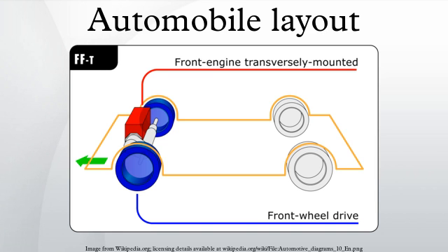Characteristics. Front-wheel drive gives more interior space since the powertrain is a single unit contained in the engine compartment of the vehicle and there is no need to devote interior space for a drive shaft tunnel or rear differential, increasing the volume available for passengers and cargo. There are some exceptions to this as rear engine designs do not take away interior space. It also has fewer components overall and thus lower weight.